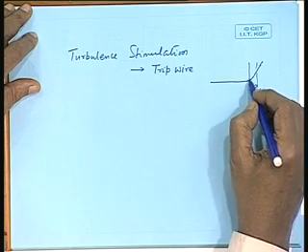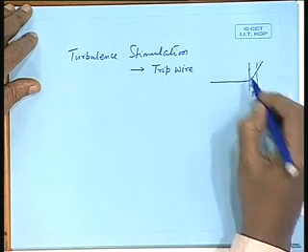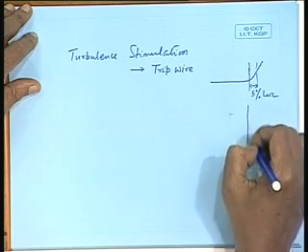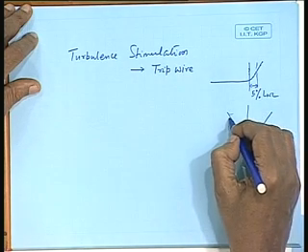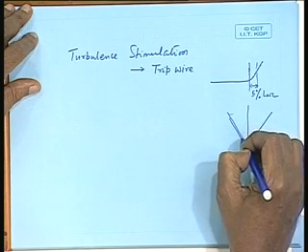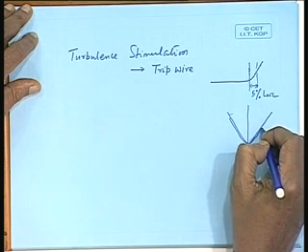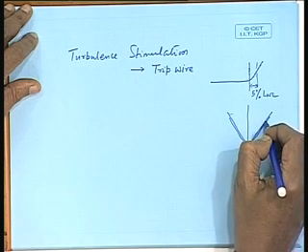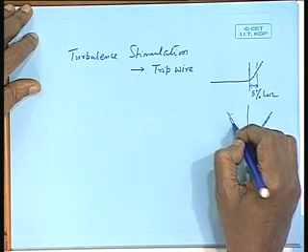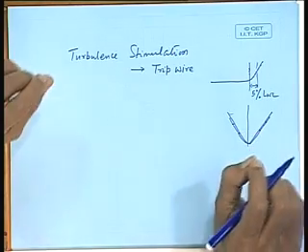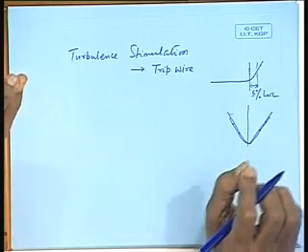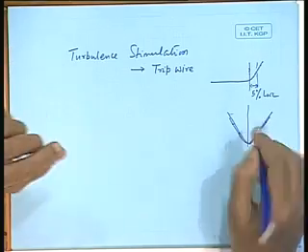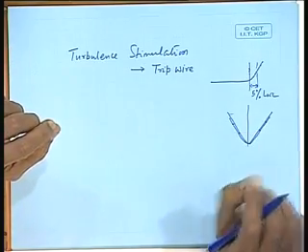So, I can put a tripwire here, that is, if I draw the section here, the section of the ship may be like this. I put a small tripwire all along the model with small anchors holding it by pins. If I have got a wax model, I can put pins and hold the tripwire, small pins which will insert themselves into the model.